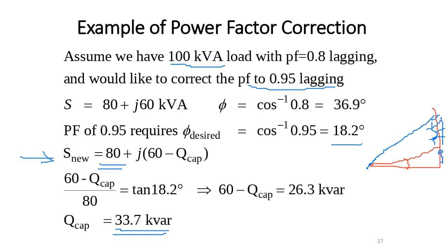Okay. So the capacitor does not absorb reactive power. It depends on the convention that you use. Here we use delivering: the capacitor must deliver 33.7 kilovar. So we put it positive.